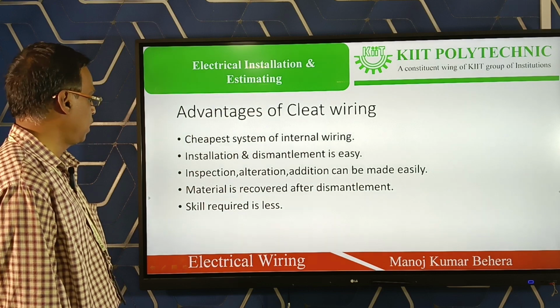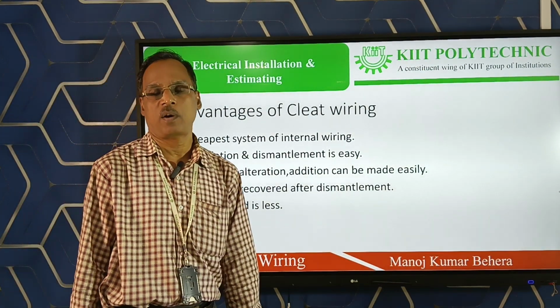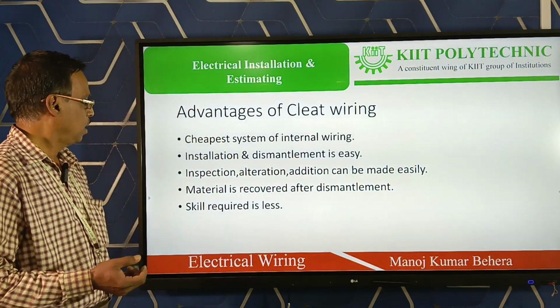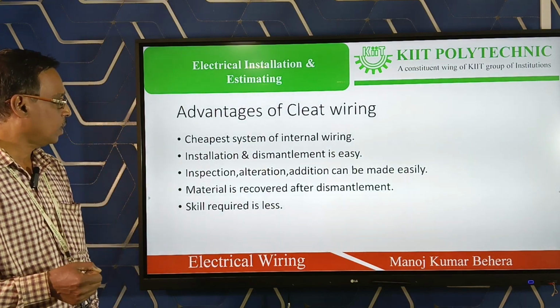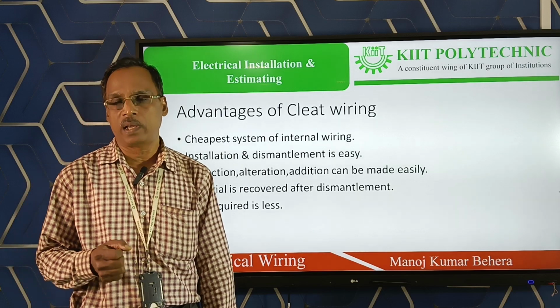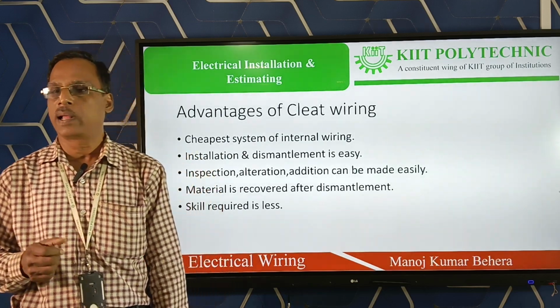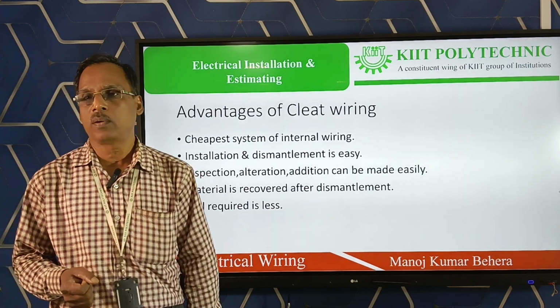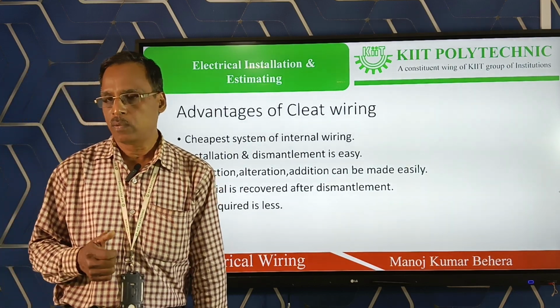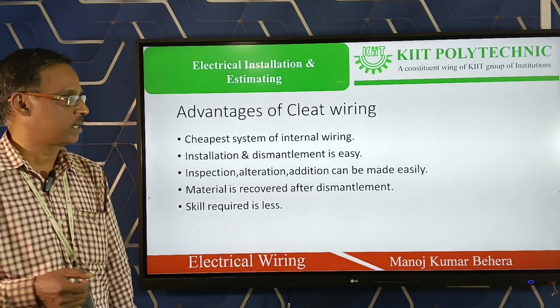What is the advantage of cleat wiring? It is the cheapest form of wiring, and installation and dismantling is easy. Inspection is very easy. We can detect the fault at any moment and less maintenance is required. If you want to dismantle the wiring, you can dismantle it immediately.